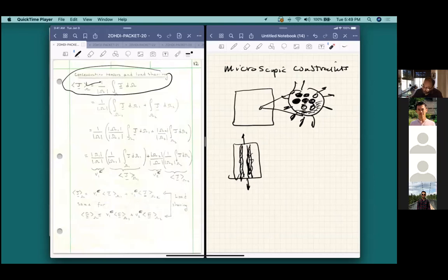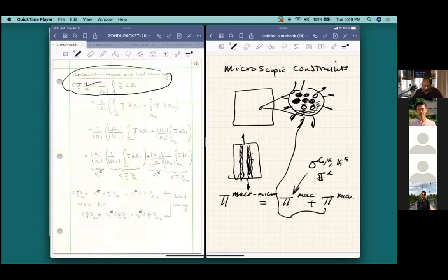Now, the main point that is important here is that when we design a material with a so-called macro-micro design, basically what we do is we take the macroscopic part, which attends to things like sigma C star, kappa star, E star, and then we also add a so-called microscopic constraint, and the microscopic constraint takes into account how much of the load is actually carried by each of the different phases. So the different phases are represented, and how much load they carry is given by this term here, but I'll save that for Thursday.